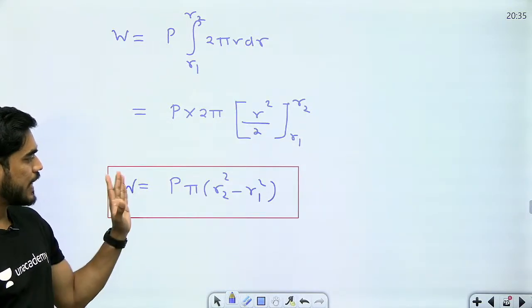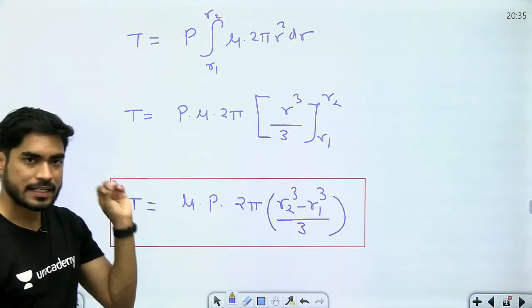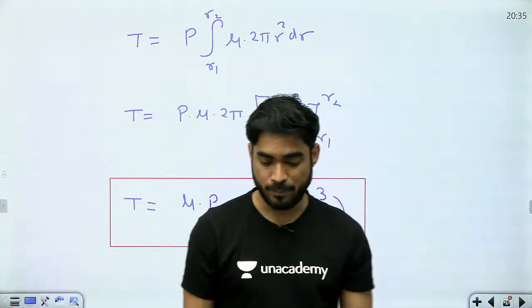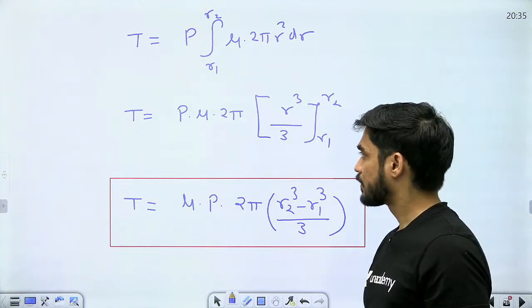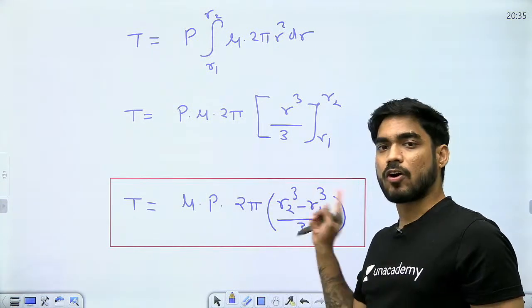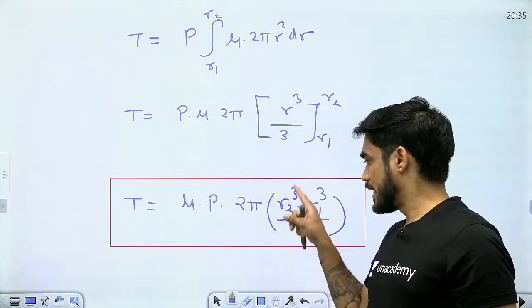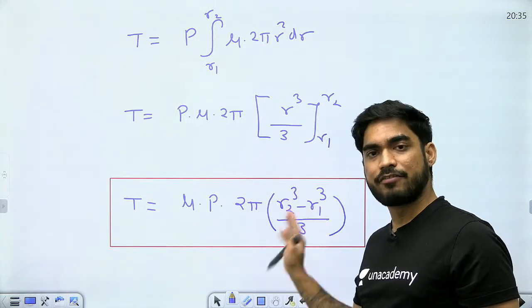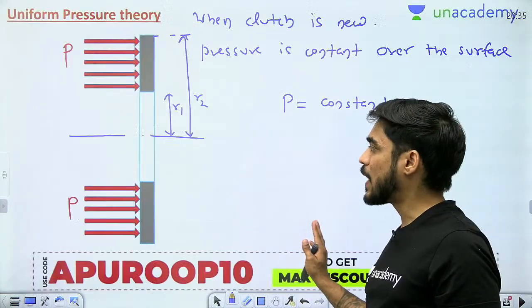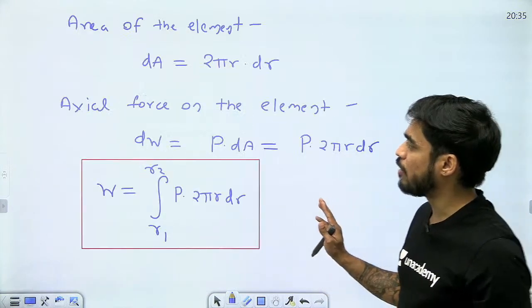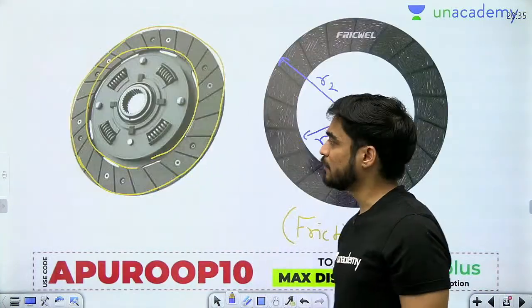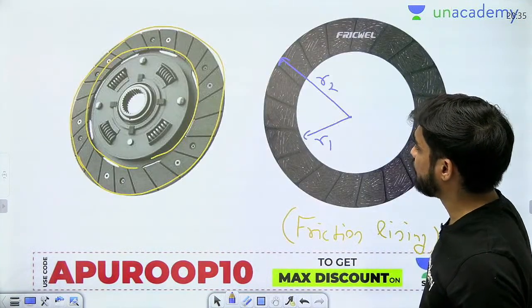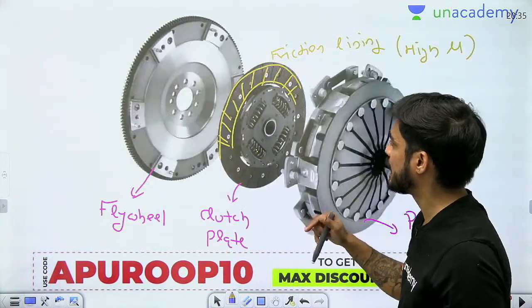Okay, so we have these two relations for the plate clutch. This is a single plate clutch. Now understand beta, this particular torque relation is derived assuming that the torque is transferred only from one side of this friction lining. But practically you will see that the friction lining will be on both sides, right?